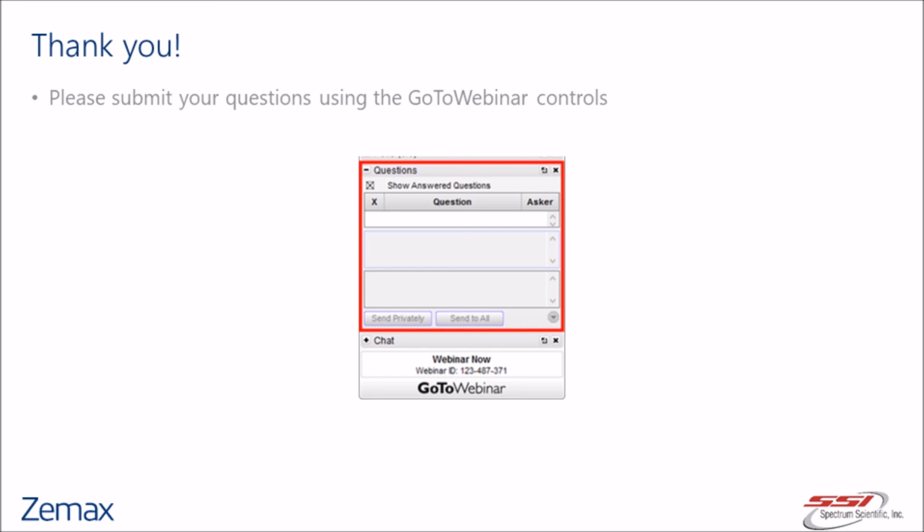You could also use an off-axis piece of that. If your ripple is not symmetric about the vertex of your part, you could use an off-axis chunk of the Zernike phase surface to put that in. You can put in ripple with an extended polynomial too, which would separate the x and y coordinates and give you a little more flexibility in how to designate how to get that ripple in place.